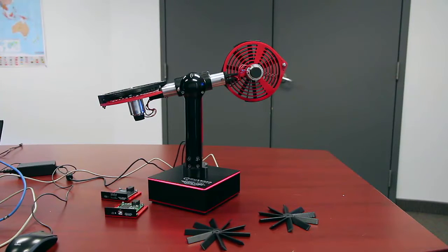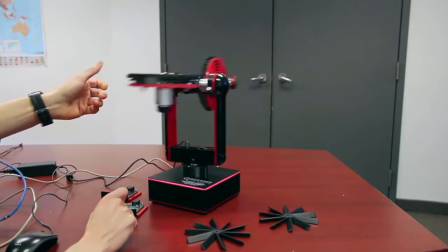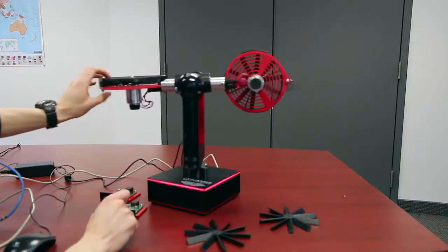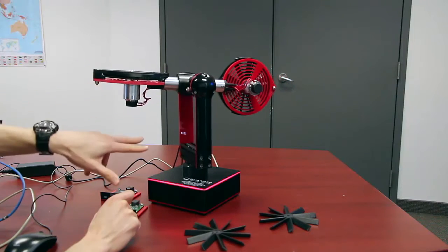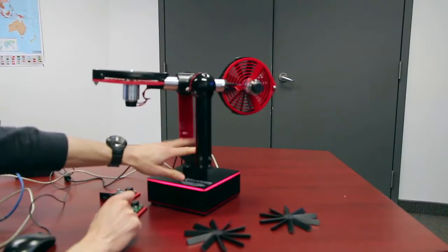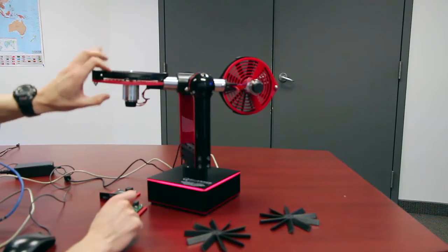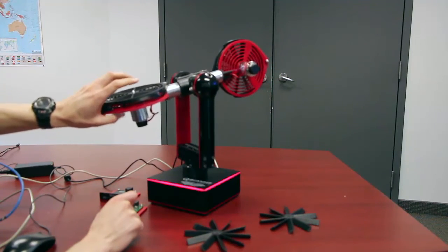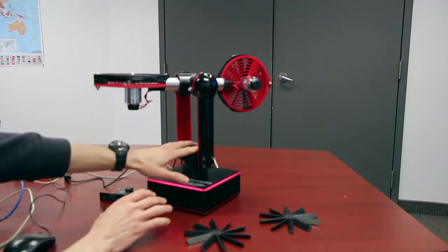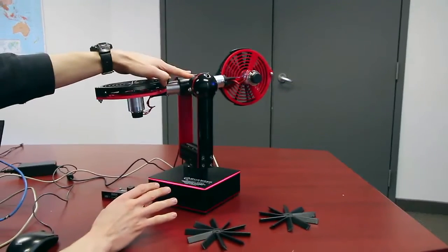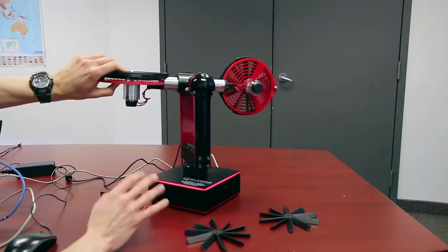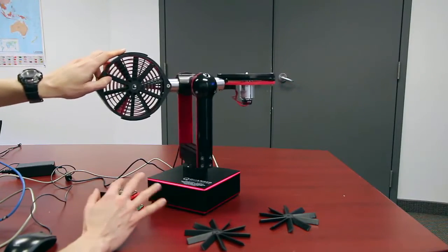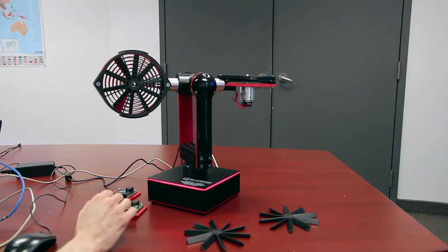Now let's talk about different configurations you can do. As you can see here, the yaw has a slipper design that allows you to move it continuously 360 degrees. But you can choose to lock the yaw if you want using the Allen key. If you want to conduct experiments only in the 1-DOF configuration, 1 degree of freedom pitch, you can lock the axis and just do that. Similarly, you can lock the pitch. You can also adjust the angles of each rotor. We'll go through 3 different configurations today, so you can have an idea of how you can change between different configurations.